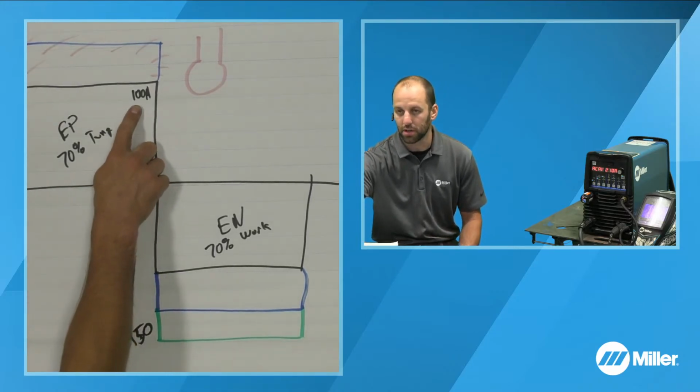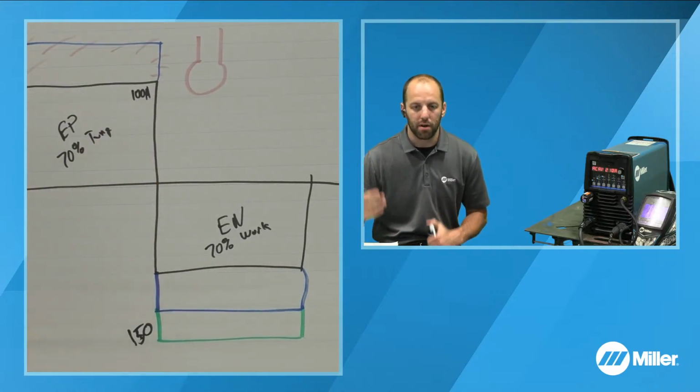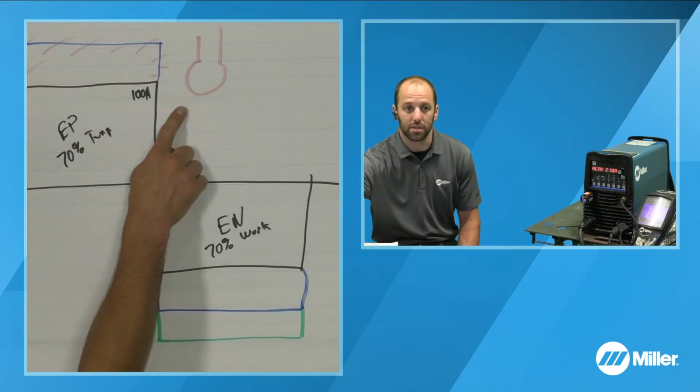And that's going to be critical once you start getting above, let's say, 200 or 300 amps in particular. You probably want to start skewing your independent amperage or your ratios, so that you don't have excess heat on the tungsten.